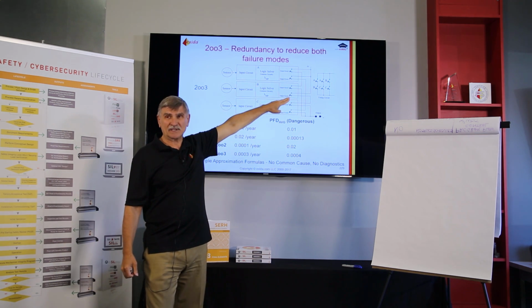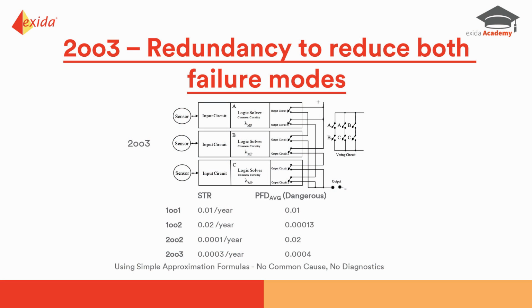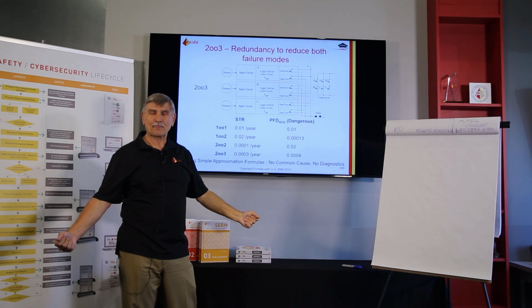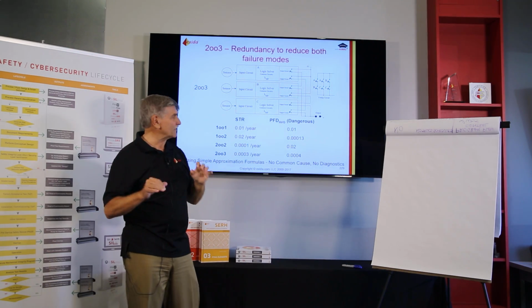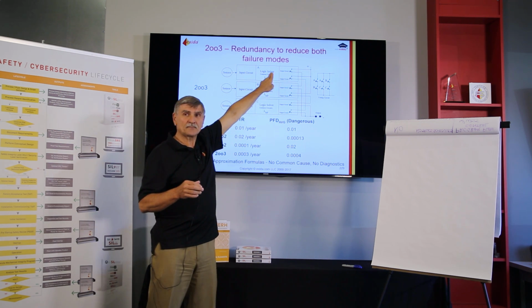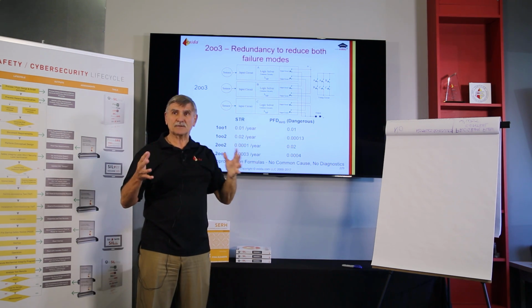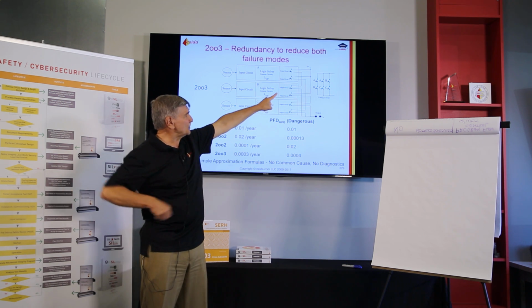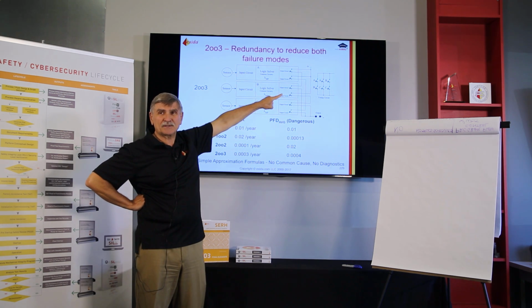Look at that output switch. This works because not only is there 3 full sets of electronics, but each set has 2 output switches. We take those 6 switches and wire them 2 in series and 3 sets in parallel. Think about it a minute. What if the A subsystem fails dangerously? Okay, short out those 2 A switches.